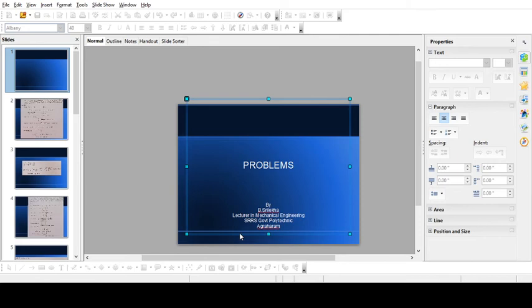So it is on the top face, 100 by 250. It is 4 meganewtons. Next, a tensile load of 2 meganewtons on its 50 by 250 face. So this is 50 and this is 250. It is nothing but its face, and it is 2 meganewtons. Now the E value is given and Poisson's ratio is given. You need to find the change in the volume of the bar.